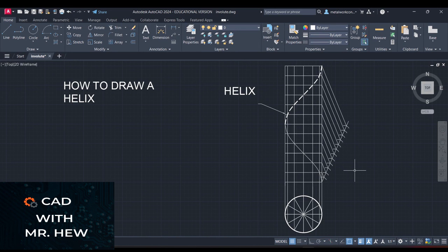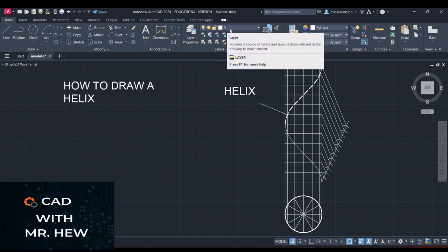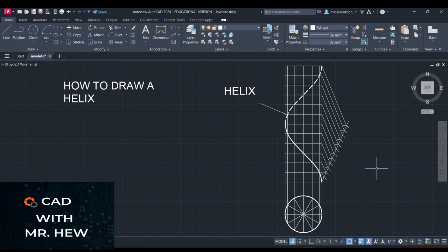And what we're gonna do also, we're gonna darken the helix that starts from point 1, points 1, 2, 3, 4, 5, 6, 7. Okay. So if you were using the traditional pencil with the drafting equipment, you would use your darker pencil now to darken up the required helix. Okay. All right. So here is our helix, right?